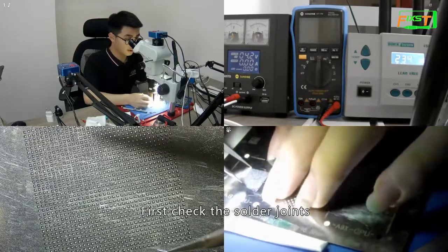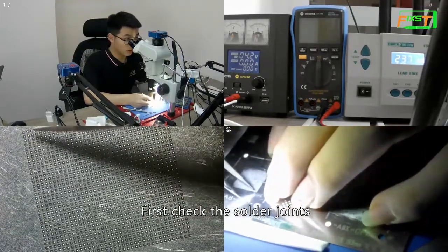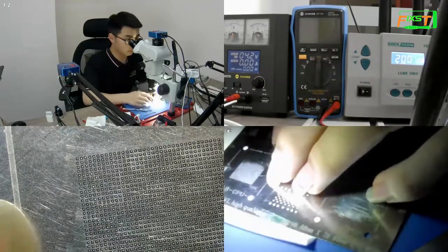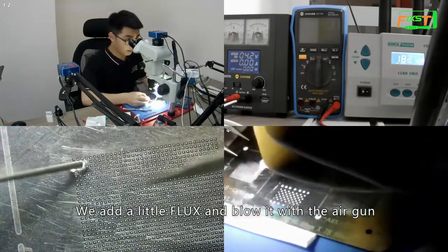First, check the solder joints. There is one pin that is not welded. We add a little flux and blow it with the air gun.